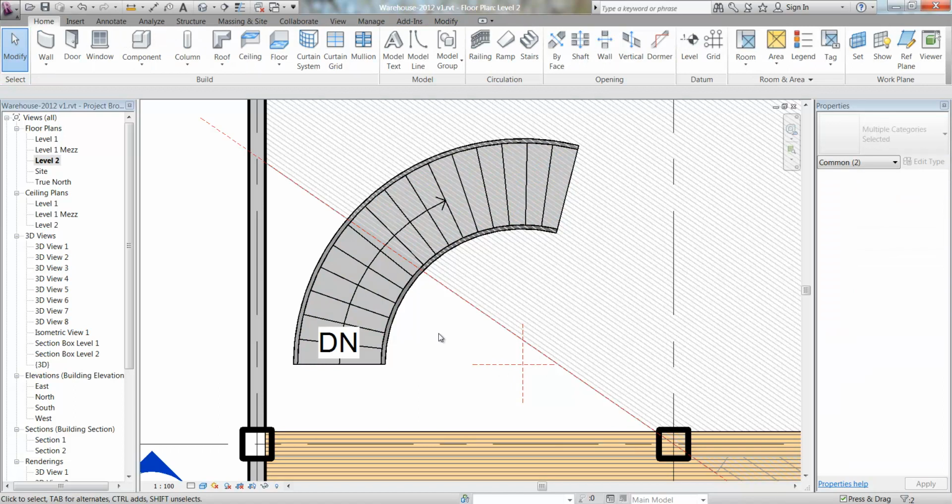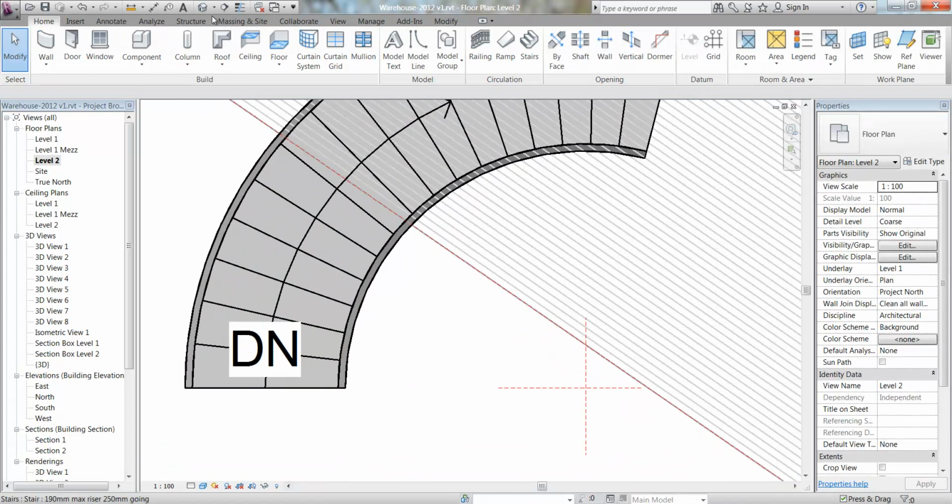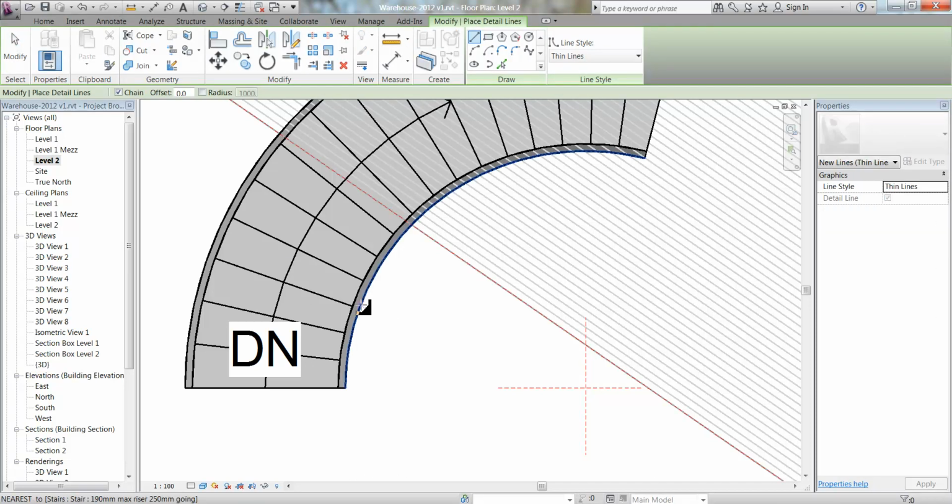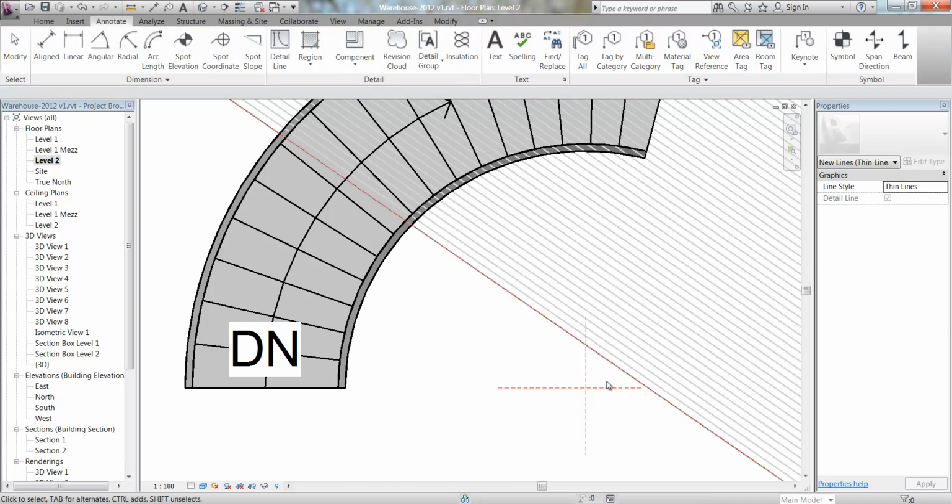And it's just a little trick, because what you find when you go to do something like, well, I'm just going to draw some lines, and I'm going to snap to the center. So SC snaps to the center, and you can see that it is snapping to where I've got the reference planes. But it won't always do that. I'll just see here if we try some other curves there. It's doing a pretty good job this time, but trust me, that won't always be as accurate. So yeah, it's just a little trick. It makes life much easier if you have that center point set out first.